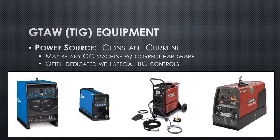Often TIG equipment is dedicated, and it provides specialized controls for TIG welding. For example, many of the machines illustrated below in the pictures provide internal gas valves and plug-ins to plug in water circulating devices. They provide high-frequency arc starters that aren't standard in most of your other equipment. So they're really dedicated for TIG welding in many cases.